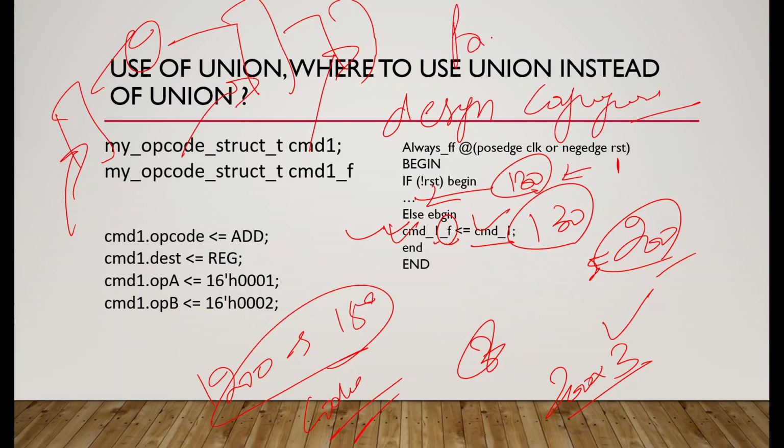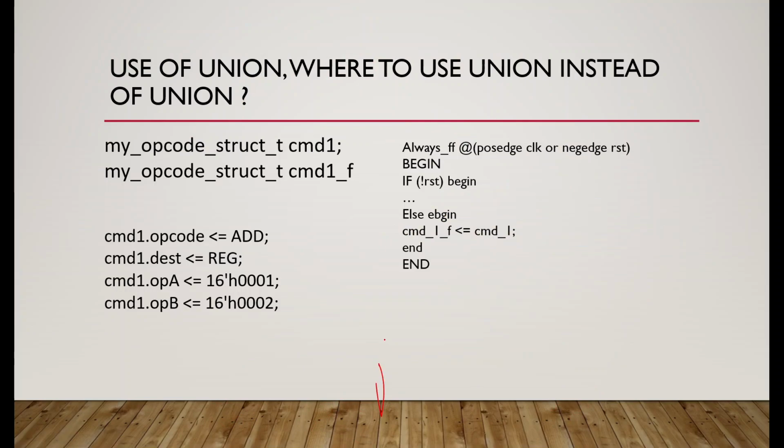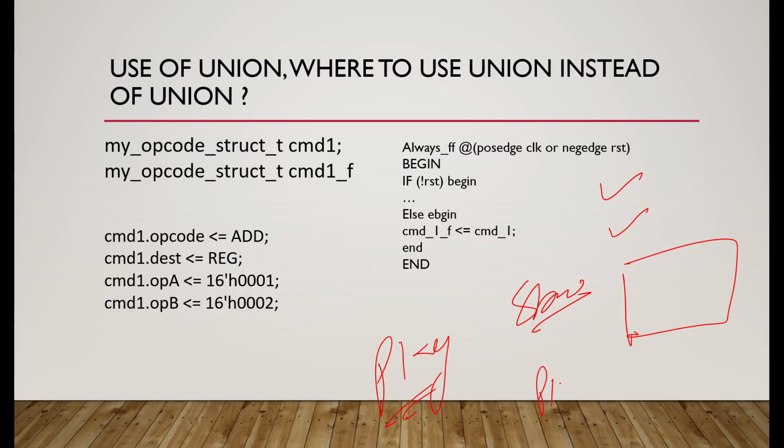When protocol changes, I will only change the package file. You know where we write the struct, when I teach SystemVerilog, I will teach how these unions and structs are written, where these are written. So we have a file called package file, dot package, for these header files, right? So we have package files for RTL, right? We only edit the protocol there in the package file, and the complete RTL itself is changed.